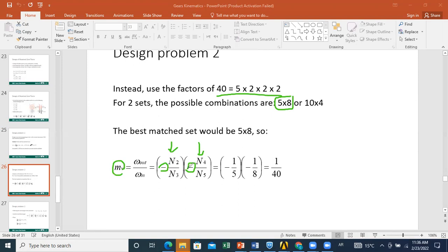Okay, so you get for your first, one of your ratios is 5 or 1/5. As I told you, you can do the design on 40 or on 1/40. In general they are used to take the configuration of reduction, because they take the pinion as input and the gear as output. Just by reversing input and output, you get 40 instead of 1/40. Okay, so they set here n2 over n3 to the first value of gear ratio. You have 1/5, and for the second 1/8.